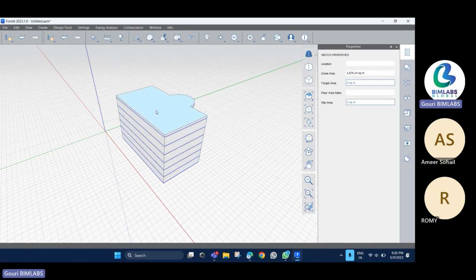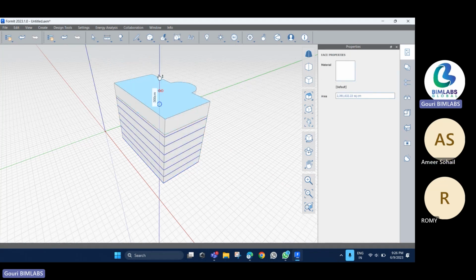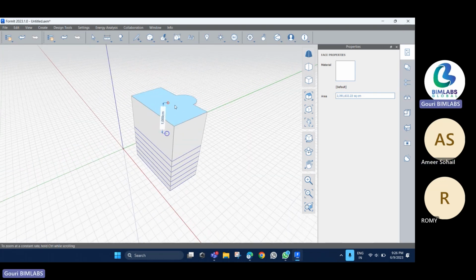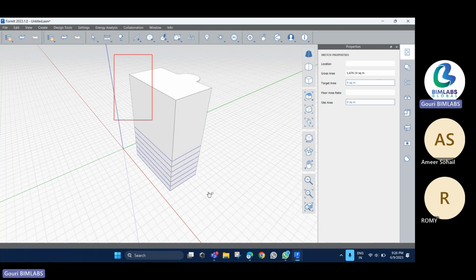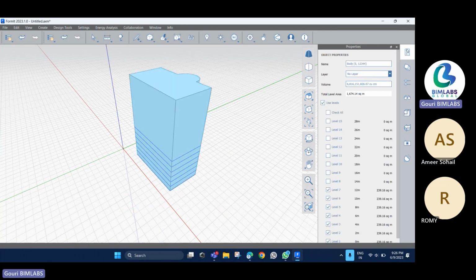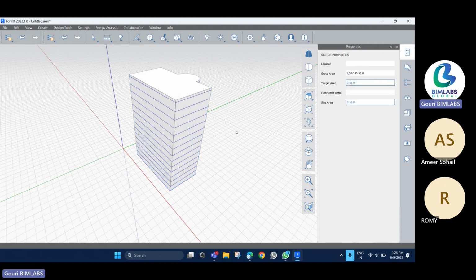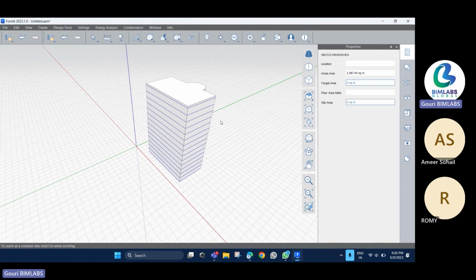Okay, so just a minute. Using this, it is providing more height. Levels are not assigned, you have to assign. Okay. Again select this one. Then go to the properties again. Then you have to activate this one. Or you can just click on the check all option. Okay. So likewise, we can create and assign levels to this conceptual model.